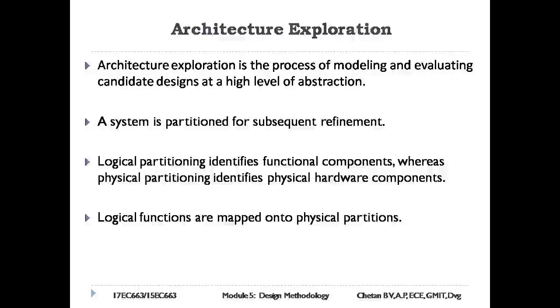Hardware-software partitioning involves mapping a given logical component to a specialized hardware component whose only task is to implement the logical component. Another logical component may be mapped to a software task run on a processor core under control of a real-time operating system.